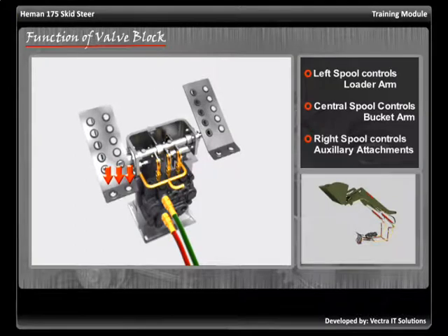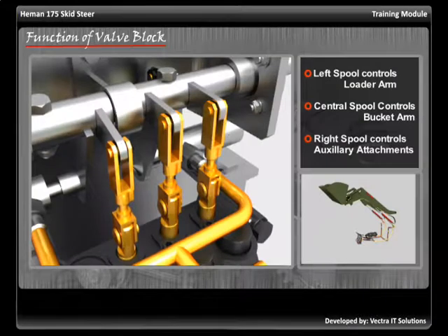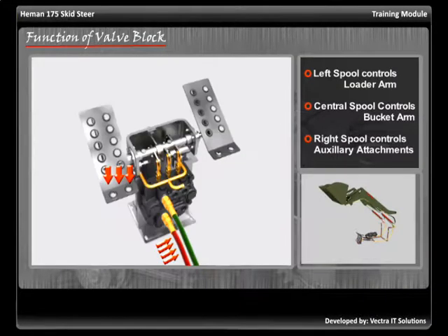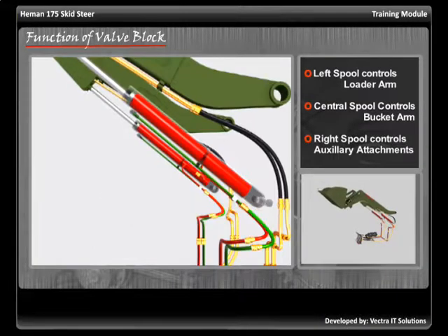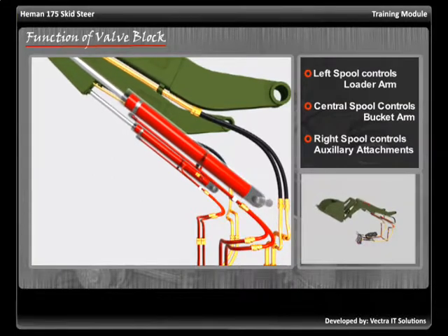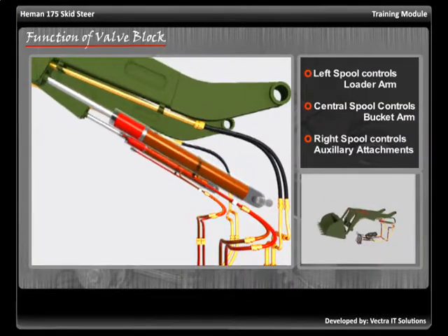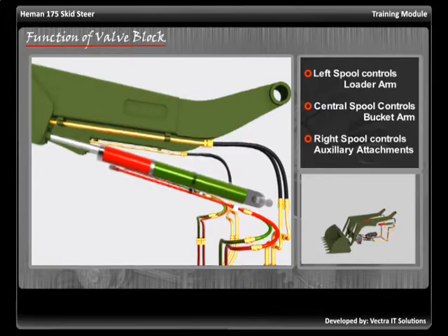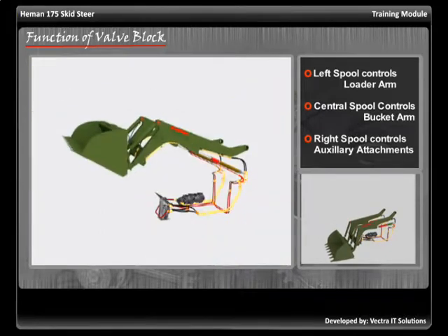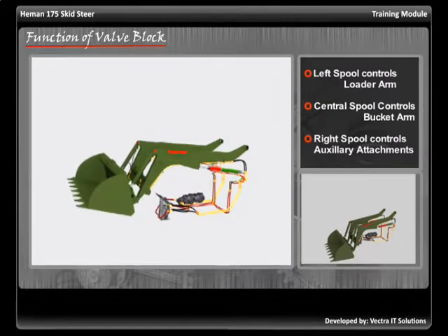Pushing the foot pedal by the ankle of the operator reverses the entire mechanism. The spool gets pulled up. Lower port becomes the escape route for the pressurized oil, and the pistons of the cylinders are pulled in the opposite direction. This collapses back the extension rods of the cylinders, and brings down the loader arm proportionately.